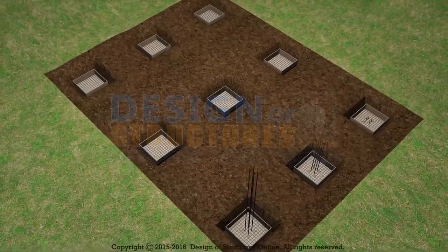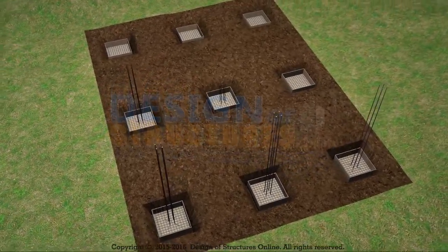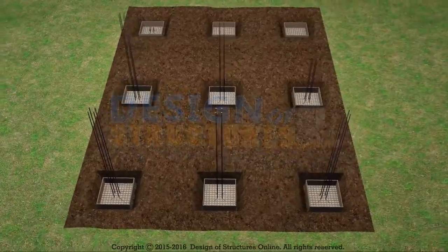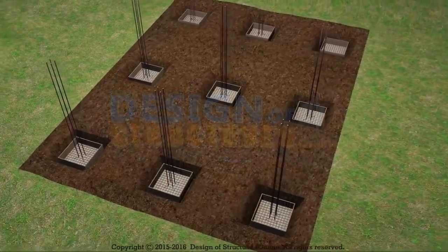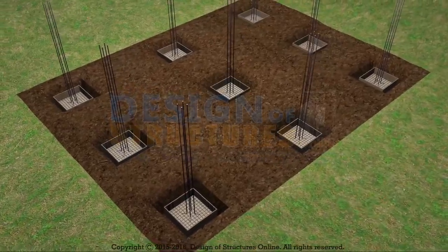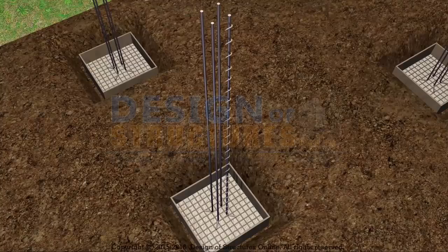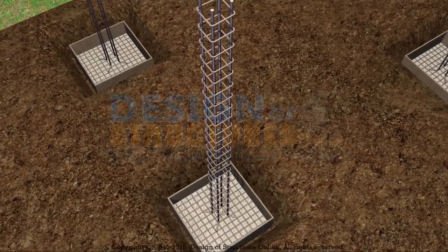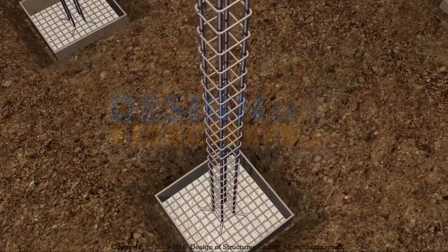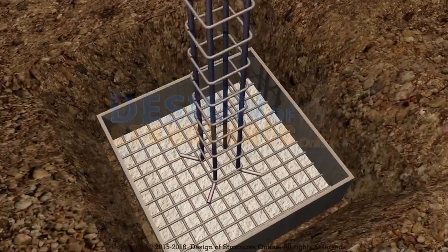Reinforcement shall be as per the bar bending schedule prepared according to drawing. The reinforcement shifting and binding shall be started as soon as shuttering is completed. Reinforcement binding shall continue as shuttering work progresses.